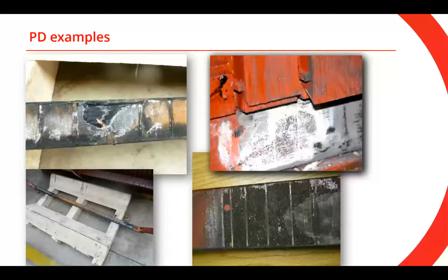And here on the left-hand side on the top, you can see the stator bar with the earth fault. So for that particular stator, it was too late. Unfortunately, this particular customer ignored very high partial discharge and ended up having an earth fault.